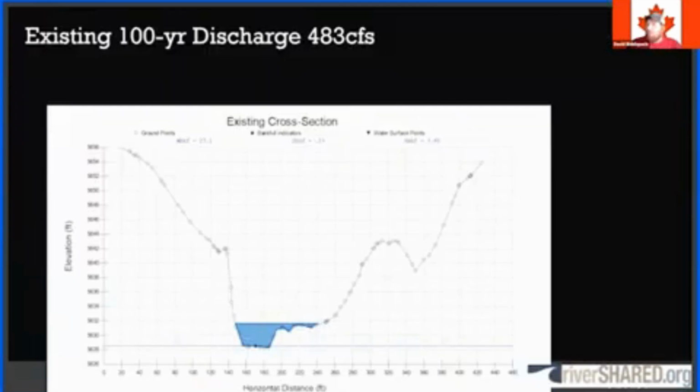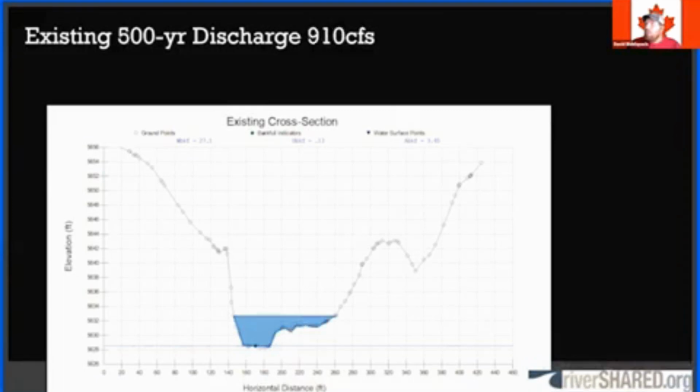One of the things that we noticed in gulches in the West is that the shear forces at the 100-year discharge, the 200-year discharge, and the 500-year discharges don't significantly change because the distribution of the average boundary shear stress spreads out and it gets wider as it gets higher. And this is one of these things where it kind of helps us understand how gullies have formed in time and why we can take such a steep drop in places where we have sandy soils. Usually it's because we have floodplains that have been able to be readjusted to this average boundary shear stress.